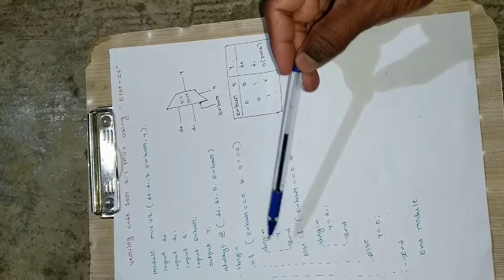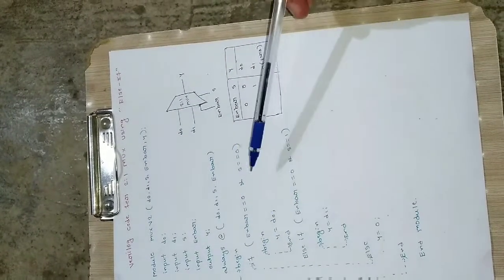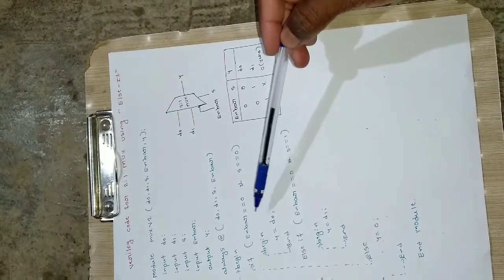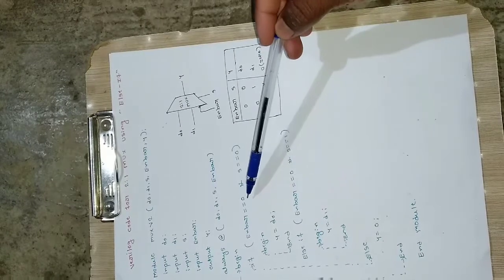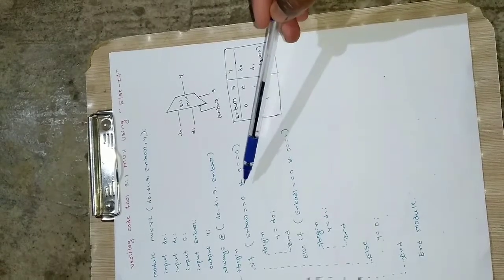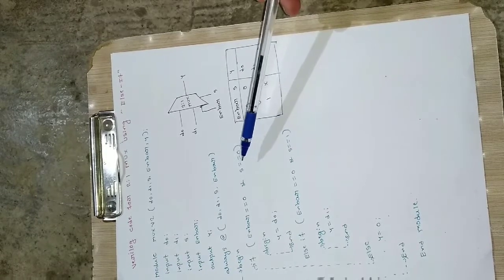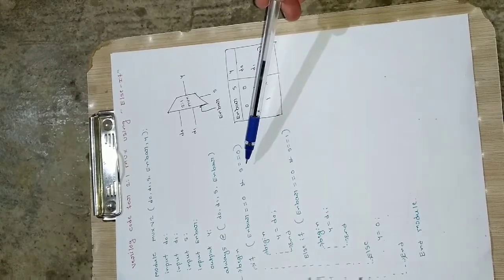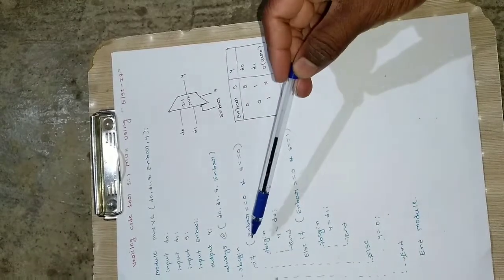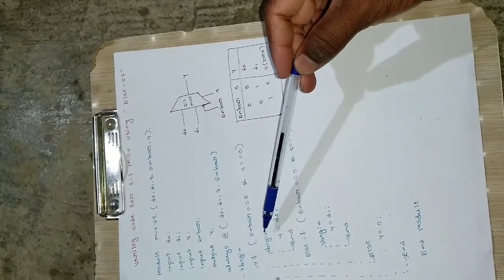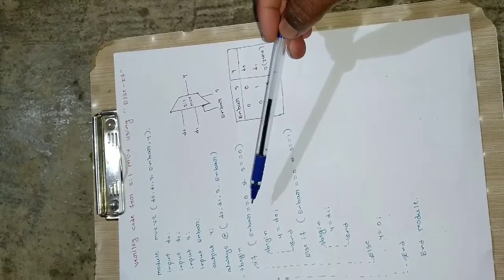So for this always we will be having a begin. In the begin we are using an else if statement. So in the bracket we have to write the condition: enable bar double equal to 0. This means enable bar value is equal to 0, and this is the logical and, and S value is equal to 0. Note that we should only use the double equal to here. For this if we will be having a begin. In Verilog, for each and every if we will be having a begin and an end.